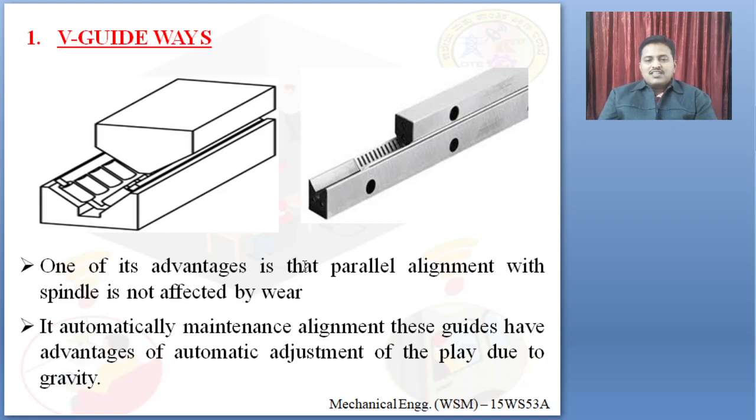One of its advantages is that parallel alignment with the spindle is not affected by wear. Next, it automatically maintains alignment. These guides have the advantage of automatic adjustment of play due to gravity. So it will automatically adjust, and any small jerk motions or stick-slip effect can be handled easily without any defects.